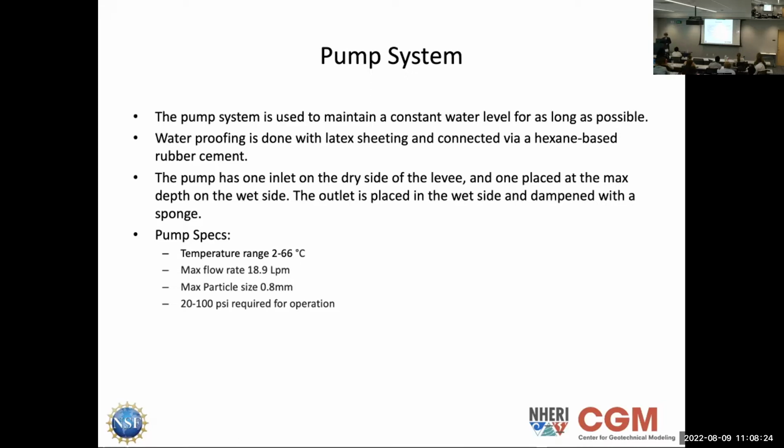The waterproofing was a very interesting experience for me. I had to do some research into latex sheeting, and we found that a hexane-based adhesive is the best way to adhere latex. It creates a contact weld that is waterproof. And to be safe, we are also using a silicone sealant to seal the levee in as well.